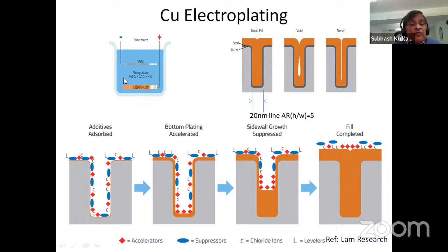And this is in an aqueous solution of sulfuric acid and copper sulfate and water, DI water. Once you apply voltage, the copper that is dissolved accelerates towards the wafers and starts depositing into these cavities that we have created, coated with the ALD process of a seed material.